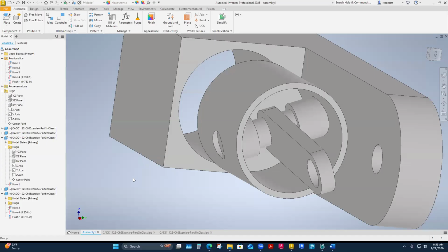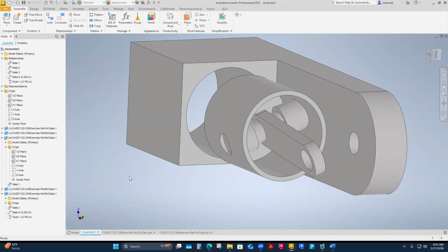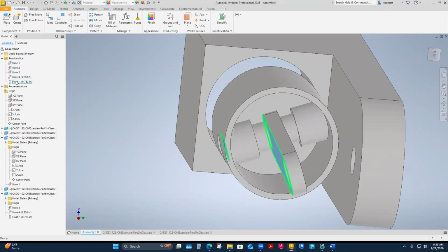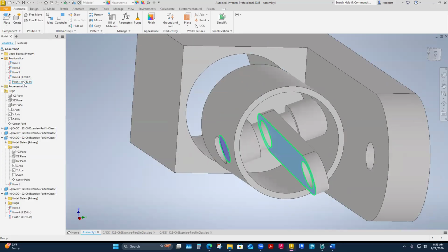Back in here, guess what? I did a few constraints you didn't see, but they're in the book, so I'm not too worried. Here I'm just exploring the ones that I applied. Here's the quarter-inch offset mate that I did, and then here was my 0.7825, which rounded to 0.783 offset. You can change these here. If it wasn't right, you can edit these. If I just single select, it gives me access to immediately do a dimensional change on the constraint.